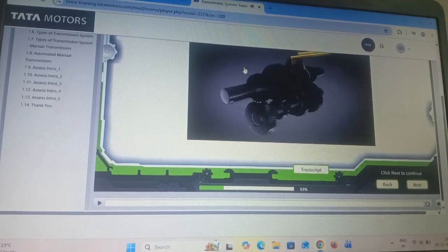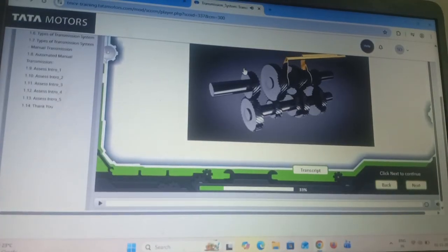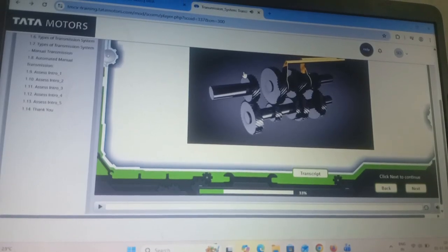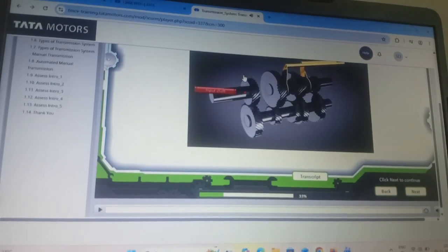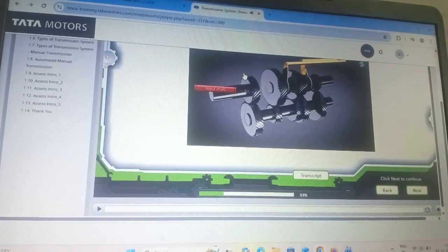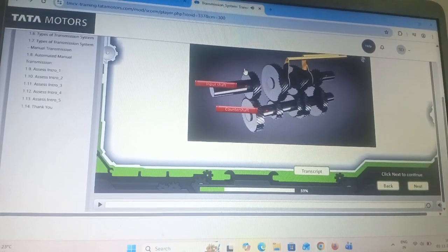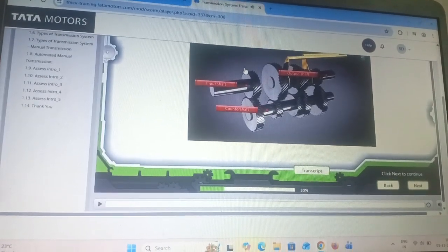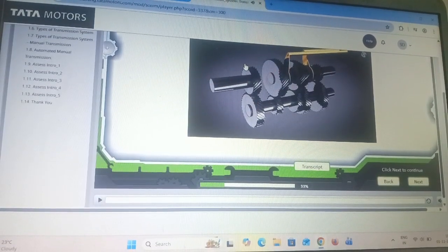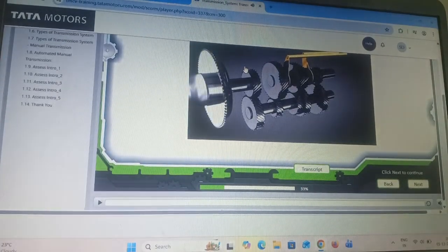In modern cars, 5-speed or 6-speed transmissions are usually used. Here, however, a very simple explanation is given with the help of a 4-speed transmission. The input shaft is connected to the engine. The rotational energy of the input shaft is transferred to the counter shaft that transfers its energy to the gears of the output shaft. The output shaft is connected to the wheels of the vehicle. The power flow between input shaft and engine can be adjusted through a friction clutch.